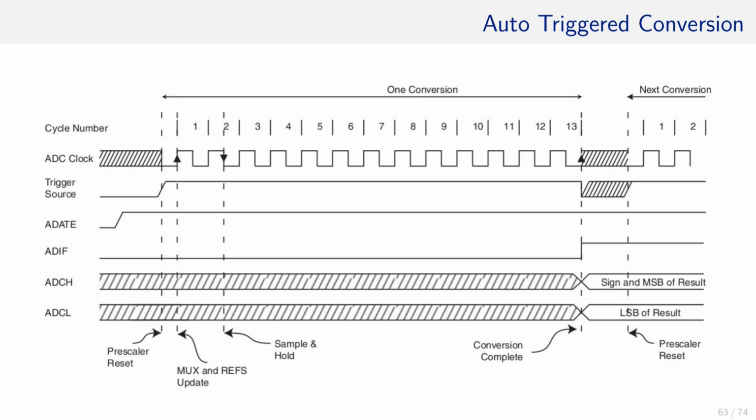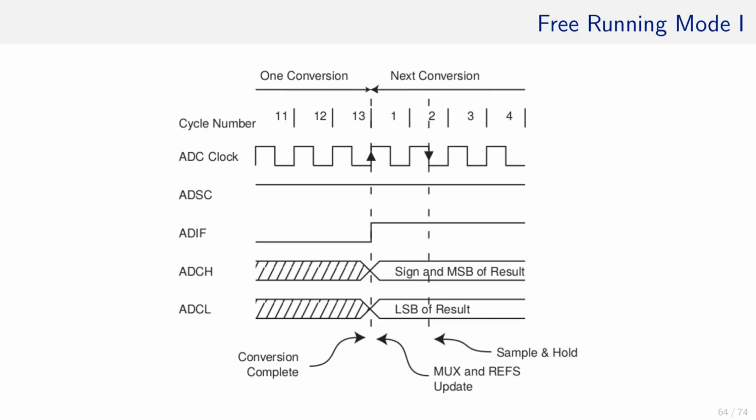In the auto-triggered setting, the ADSC bit is simply replaced by the auto-triggering source, which might be the external interrupt or a timer compare match. Basically, it is the same as the ADSC with the difference that ADATE is set. There is one interesting mode though, and that is the free running mode.